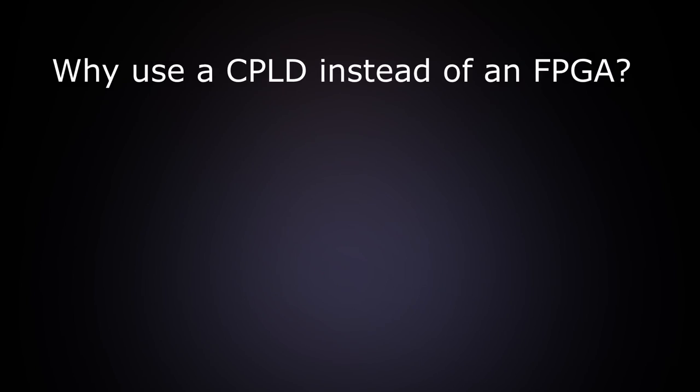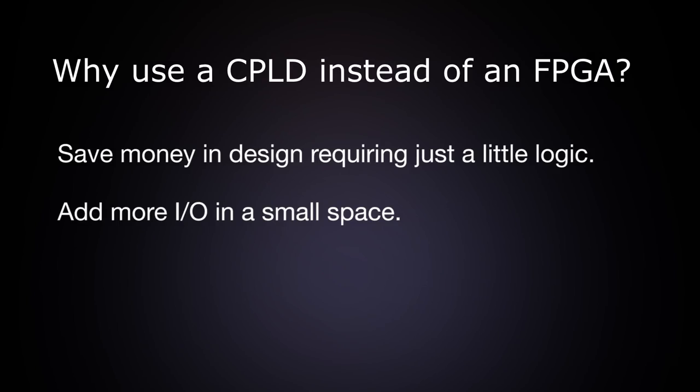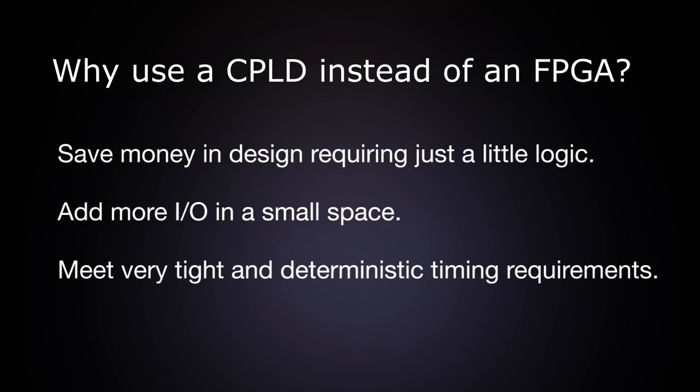Given all this, why use a CPLD instead of an FPGA? Remember, if you need just a little logic, the CPLD can be a less expensive option. It may also allow more I/O in the same space with less logic cost. CPLDs may also be the best choice if you have to meet very tight and deterministic timing requirements.